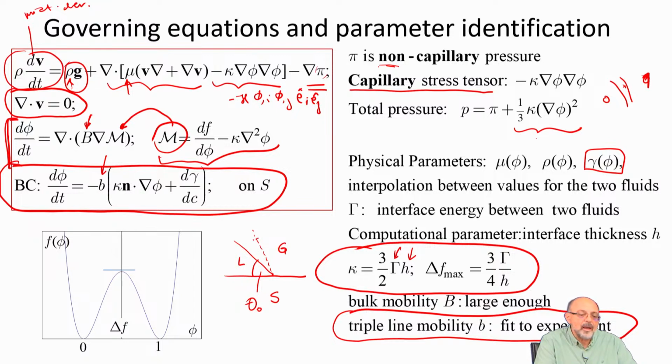So let's suppose my current angle is theta, then I have an off-equilibrium surface tension force. So this condition is mathematically equivalent to the requirement that the velocity of the triple line is proportional to the net surface tension force, the part that is not equilibrated.